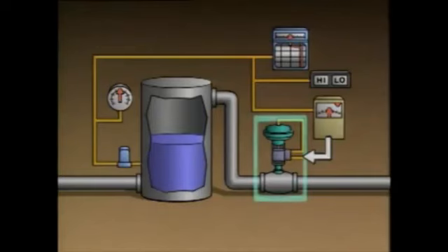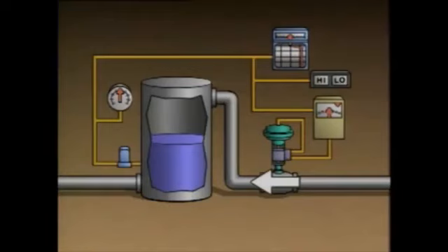This signal goes to the final control element in the instrument system. In this case, the final control element is a level control valve that can be opened or closed by an actuator. This valve controls the water level in the tank by increasing or decreasing the flow of water into the tank. In this topic, we used a system that monitors and controls the water level in a tank to identify and describe the components of a basic instrument system.